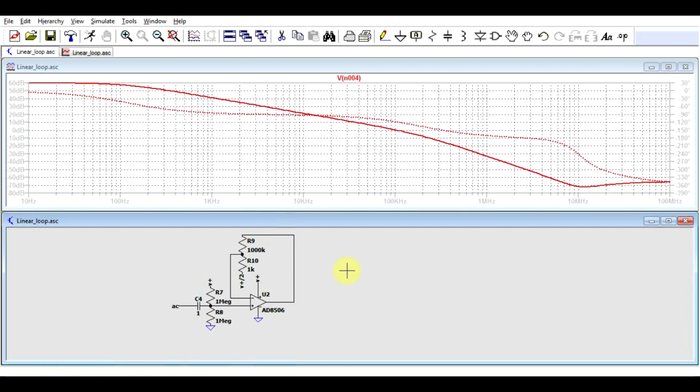So you can switch between these two simulations when performing your circuit analysis. You need to make sure that inserting an AC signal is a realistic request to which the circuit can actually respond. The same is true when the circuit is finished. You need to verify the results with a final transient simulation to make sure that, again, everything is still stable. So that about covers open loop type of circuits. But that's not really what you were interested in, right? You wanted a closed loop.